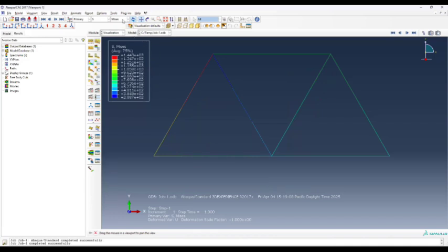But we can now see the von Mises stress. We can check S11. We can check the stresses in each direction. We can check the deformation, the U magnitude. You can probe different values. You can check at U1, at U2. But for now, at least, this is what we're looking for, for us to be able to set up a problem, to design a part.